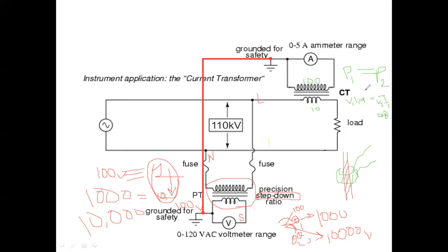So look, if we have to reduce the current, then we have to increase the voltage level, and here we are already giving a high amount of current, like 100 ampere flowing through the CT in the primary side. So we have to convert it into 10 ampere, or even less, say 1 ampere maybe.